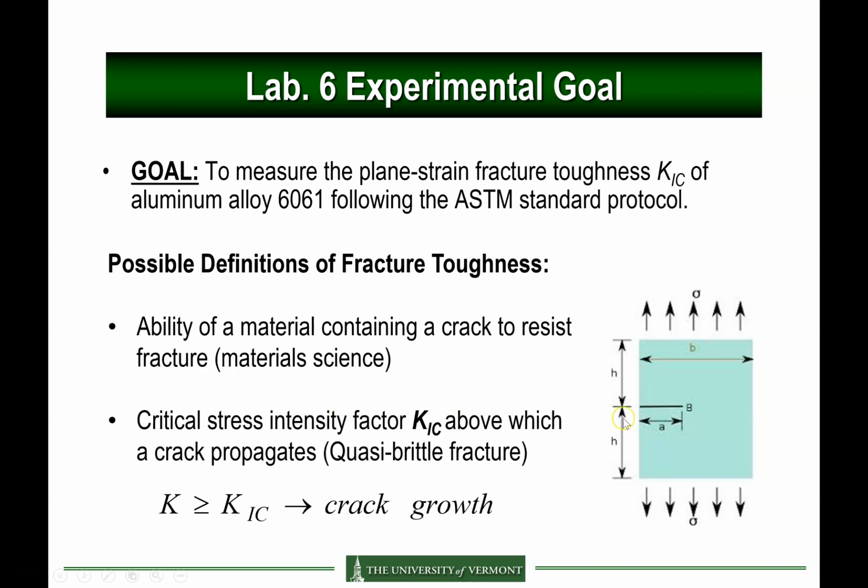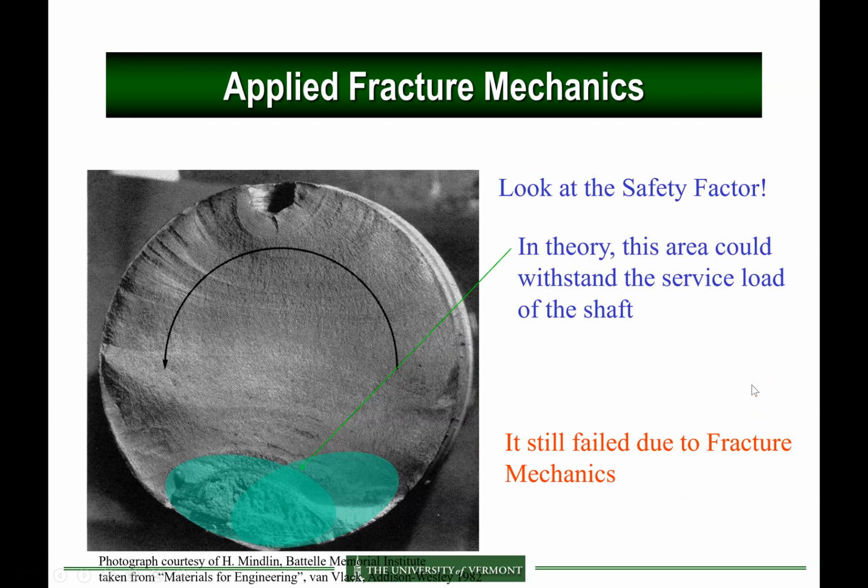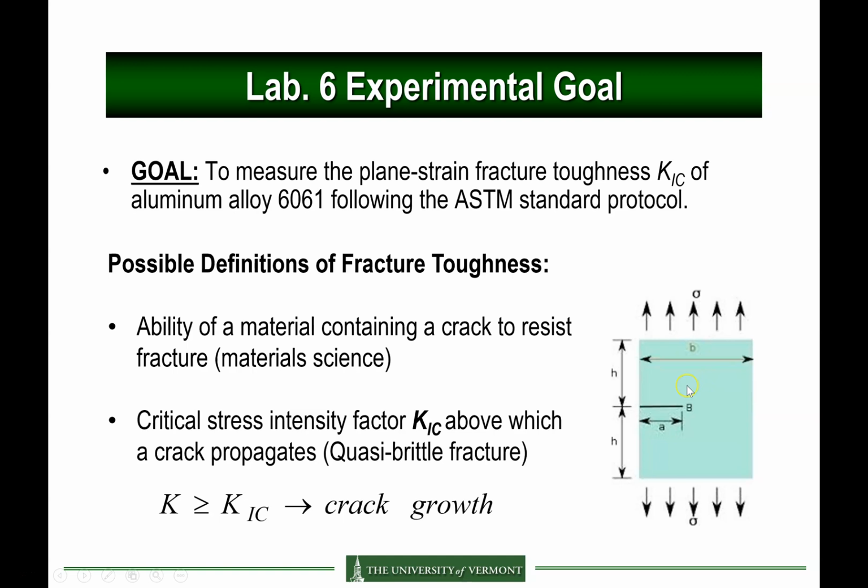So here we make the assumption that there is a pre-existing crack which has been initiated and propagated by fatigue and has attained a certain length. And so we want to know what will be the stress intensity that produces the critical propagation of the crack under constant load. Okay, I mean a monotonic load.